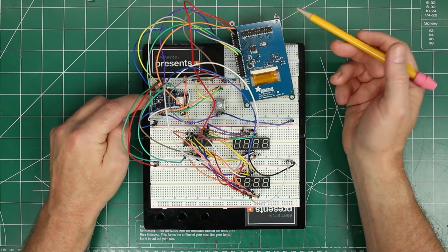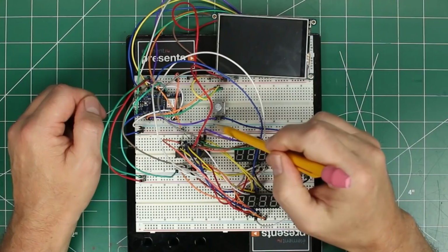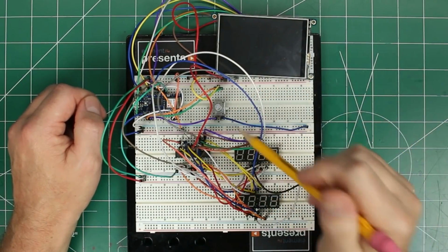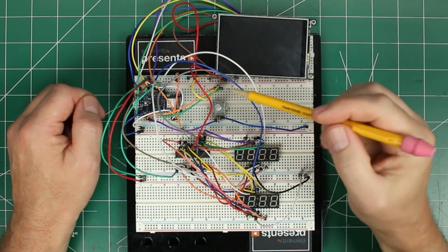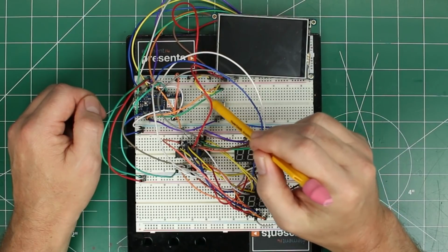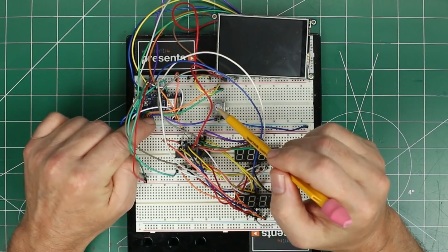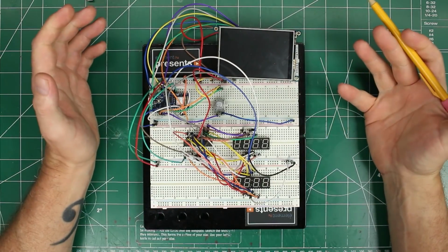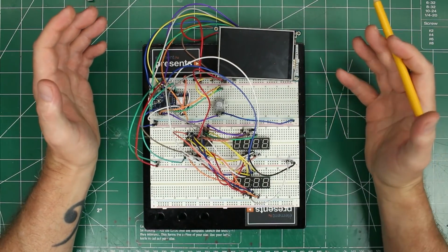The next thing is the rotary encoder. The 2 pins on the bottom are the push button. So one's going to ground, another one's going to GPIO. The 3 on the top, the center pin goes to ground, and then 2 more to interrupt GPIO pins on the Arduino. The 4-digit 7-segment displays are the part that gave me most of my problems.